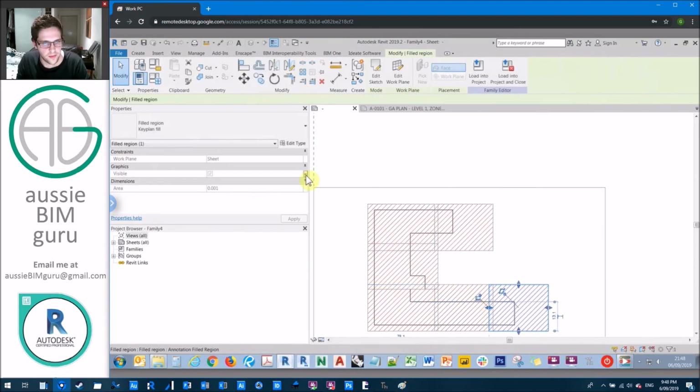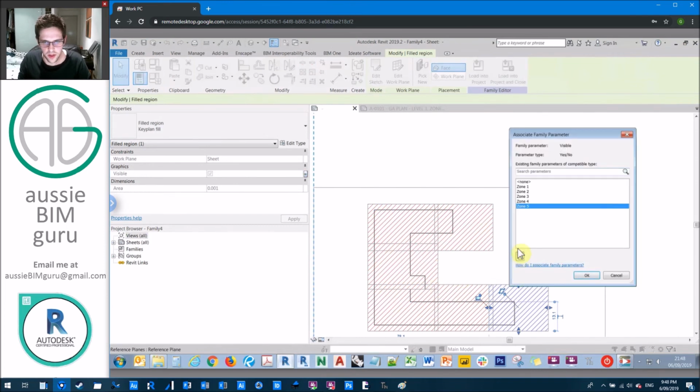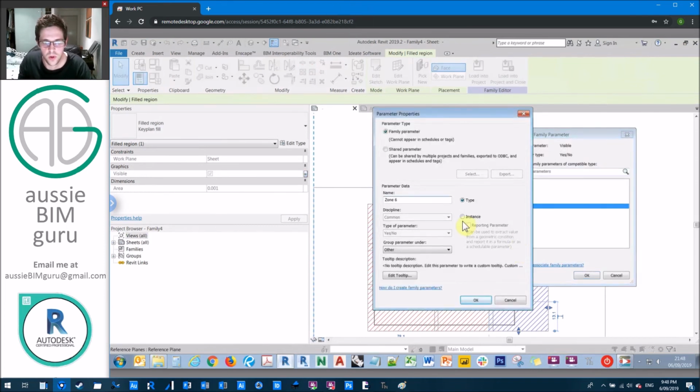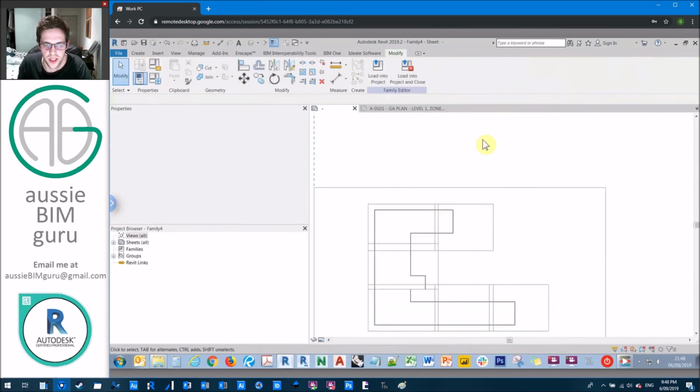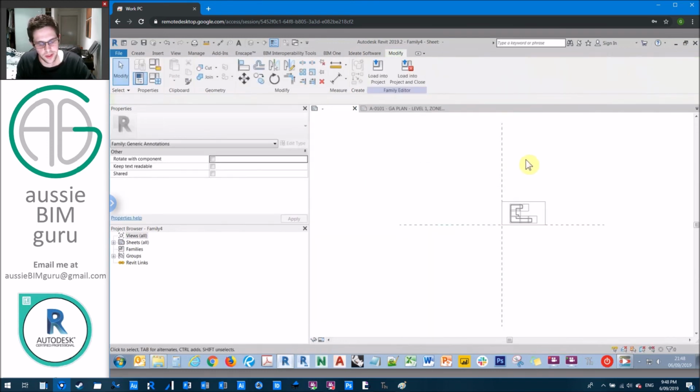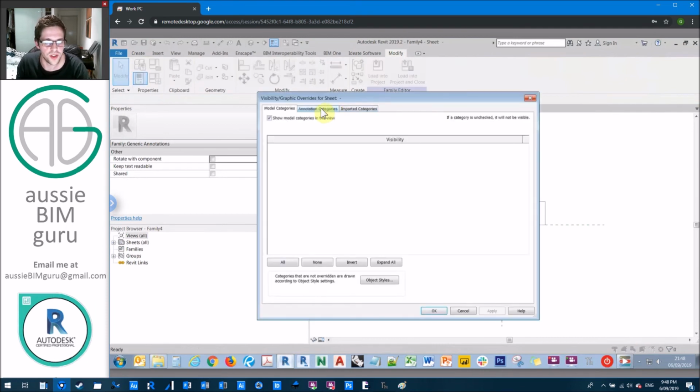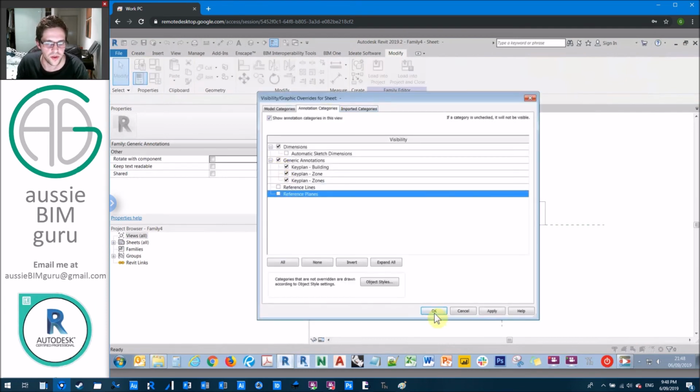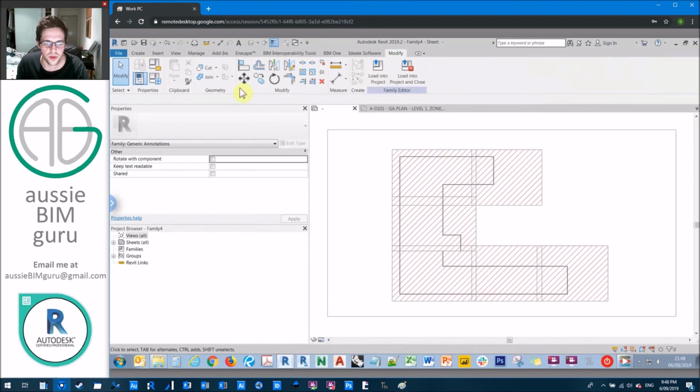And zone 6. And I feel like a CAD monkey again. Cool. So the reason that we've made them all visibility parameters is that we're going to connect these all to a number parameter to detect which zone we want to have turned on, just based on one field. So I've just turned off all the reference lines just so it's a nice little thumbnail display.